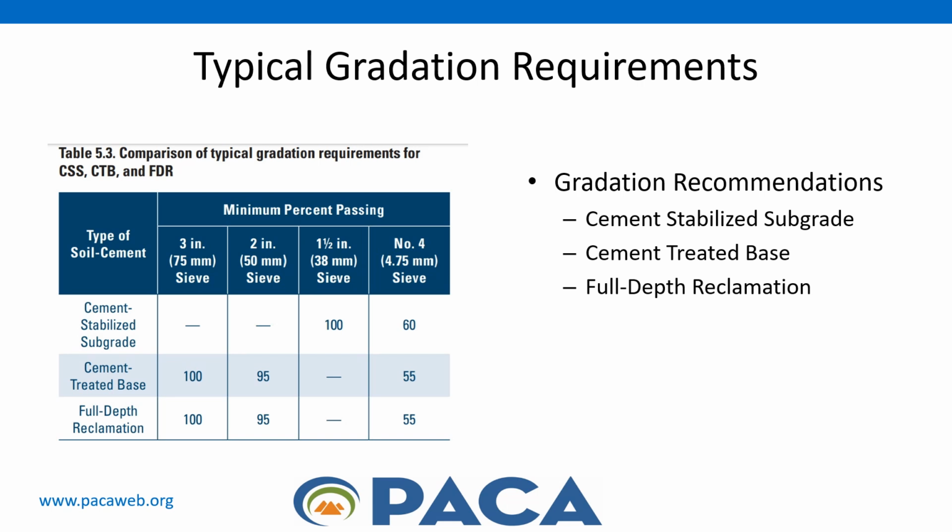Here is a chart that compares the typical gradation requirements for cement stabilized subgrade, cement treated base, and full depth reclamation. If the natural soil does not meet the gradation requirements, it may be blended with coarser or finer materials to achieve the desired gradation.